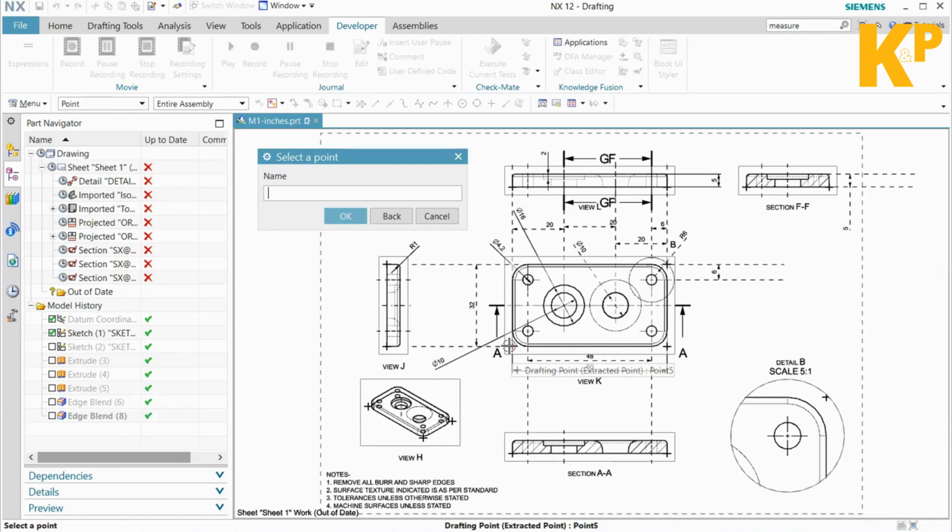Though this example only allows you to pick up one point, you can modify it with your knowledge of C sharp and NXOpen so far to include a selection of several points, or you can collect all these points you want to create the dimension with together, and you can work on a dimension builder to add the relevant dimensions into your drawing sheet. But for now, let's continue.